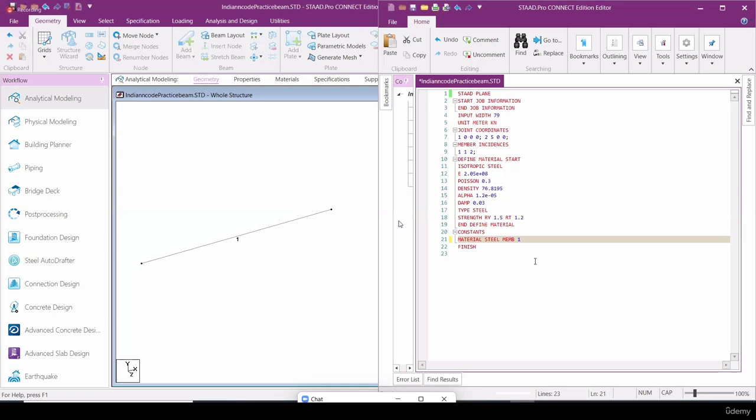Okay, after that constants, we have defined material, we have assigned the material. Now I'm going to give the properties. Properties means section dimensions. Okay, section dimensions to the particular section. For my convenience, because members, what are the thickness? 6 mm, 5 mm, 4 mm, like the thicknesses, and flanges width will be 200, 300, etc., like that, 200, 250, 280, 300.